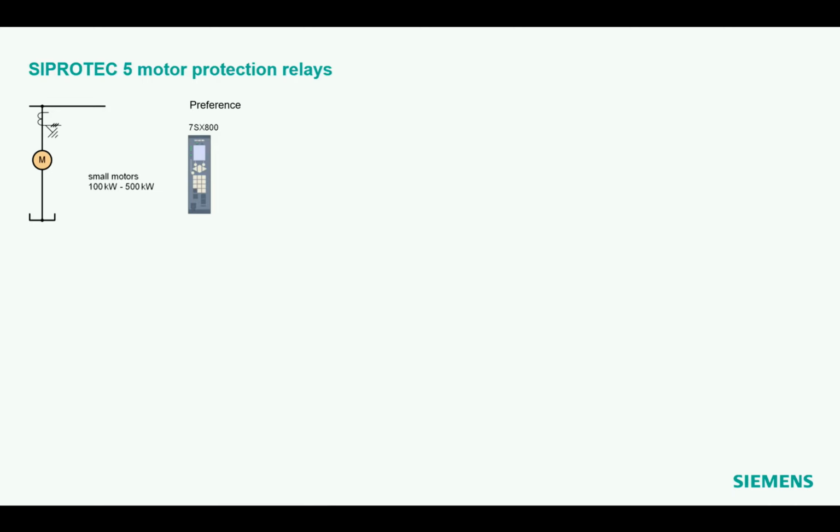And SX means it's a kind of universal relay. So this is not a dedicated motor protection relay, but it is a relay which you can apply also for the standard overcurrent protection function, for motor protection. Even there are some functions for capacitor bank protection inside and many other functions. So basically everything that fits somehow to this hardware setup.